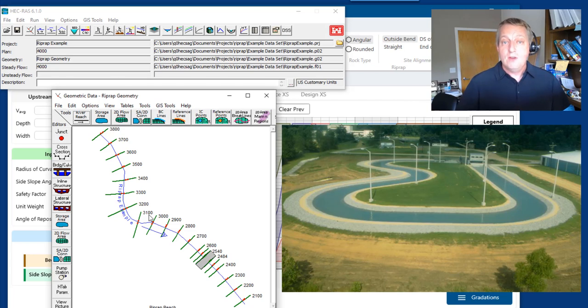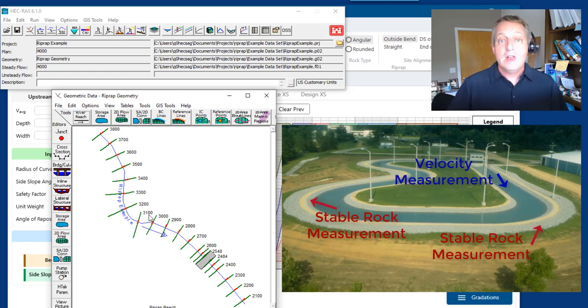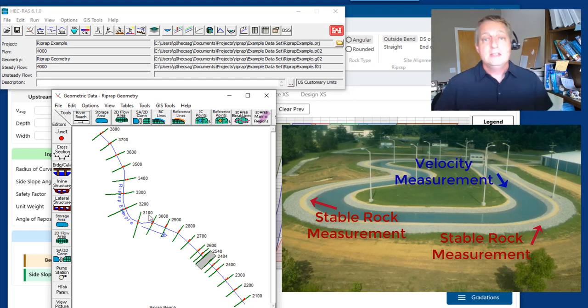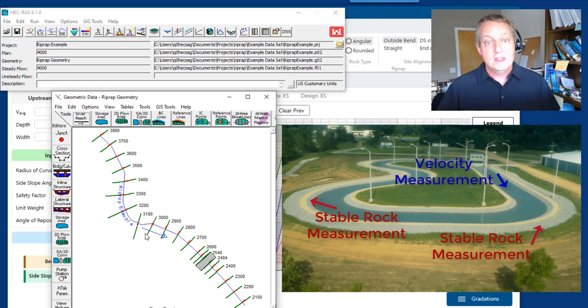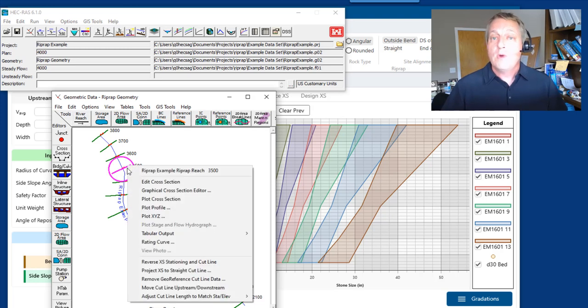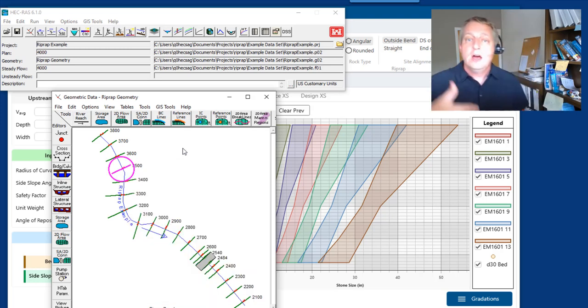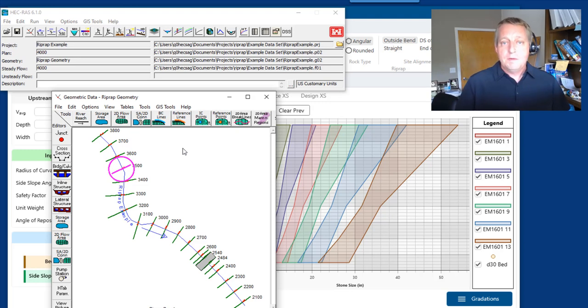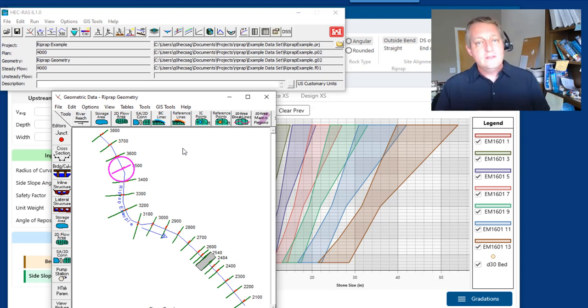When Steve Maynard developed these equations, he had a riprap testing facility, and he keyed the stable rock not off the velocity in the bend, but off the velocity upstream of the bend. And so the Riprap calculator and some of the bend scour equations that we're going to handle in the next video don't actually use the velocity for the design cross-section, but for an upstream reference cross-section, a cross-section upstream that isn't deformed by the bend, but actually is a relatively symmetrical run or crossing cross-section.